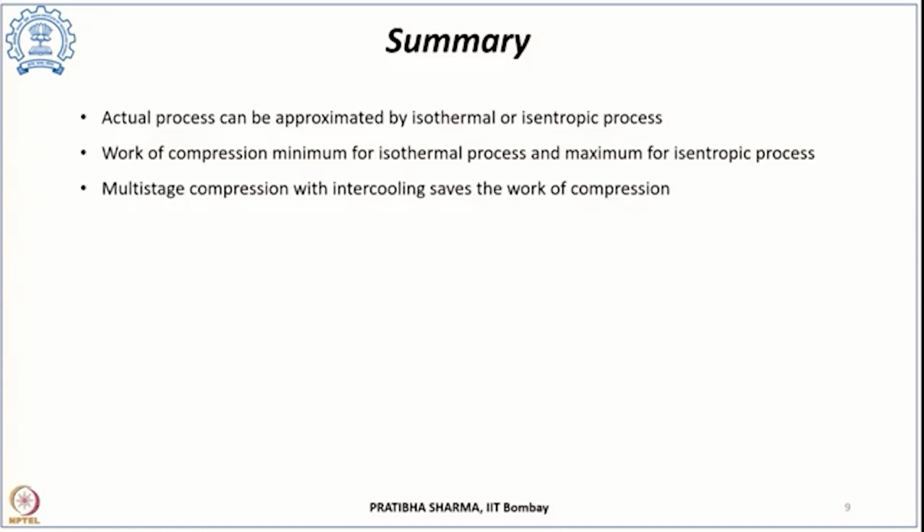So, in this class we have also seen the work of compression, considering whether the gas is an ideal gas or a real gas, which type of thermodynamic process we have modeled, and we have also looked at the compression work required for multi-stage compression with intercooling. Multi-stage compression with intercooling has the advantage that it can save the work of compression and approximate a nearly isothermal process, such that the temperature of the process is the same after every stage of compression. Thank you.